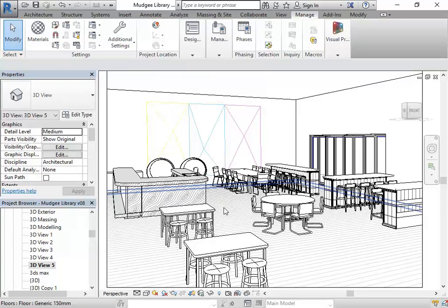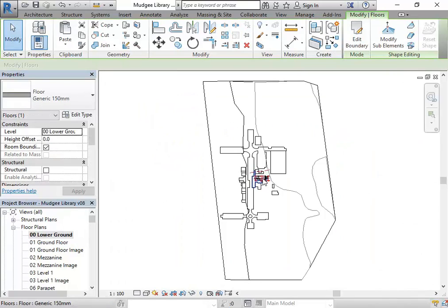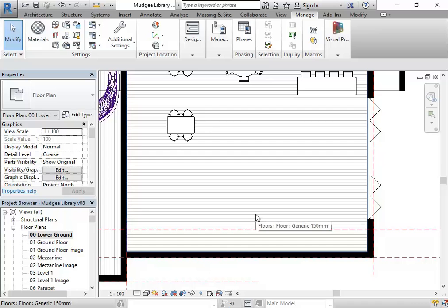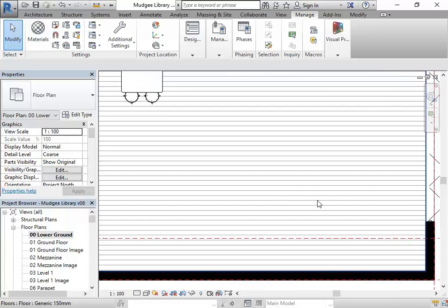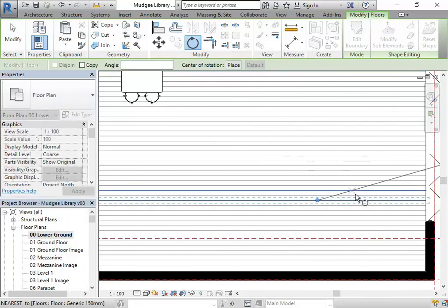So that works. There is an option as well to rotate those if you don't know. If you zoom in there, you can actually select the lines. So if you use Tab, you can select the lines in your patterns. This is actually the only way you can adjust mapping in Revit. In most other programs, there are a few more controls than this. So if I select that line, then I can use rotate and change the angle.